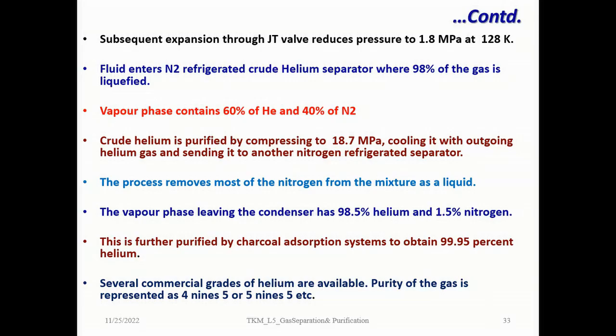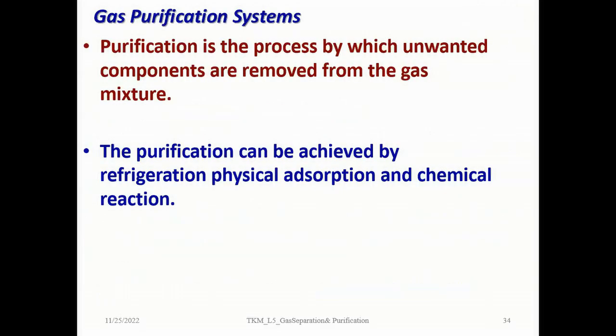Okay, let us come to the gas purification system. Purification is a process in which unwanted components are removed from the gas mixture. Purification can be achieved by several methods. Three methods are discussed here. One is refrigeration, another is physical adsorption, and third is chemical absorption or chemical reaction. Let's go through the processes one by one.